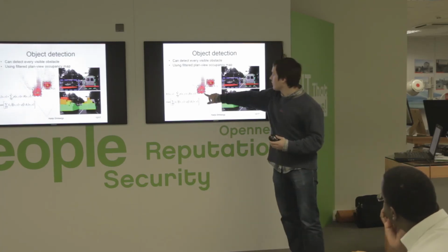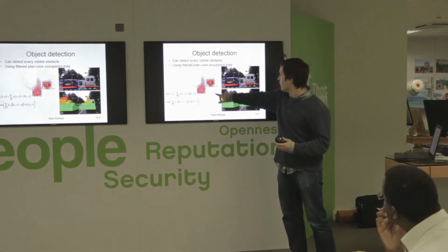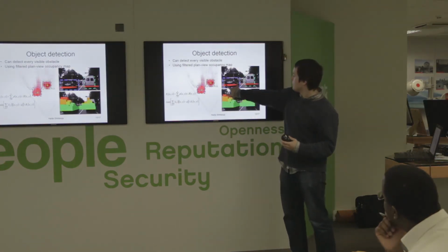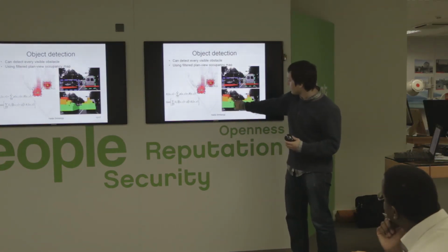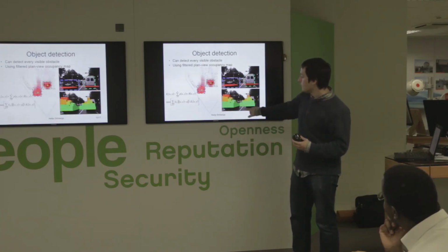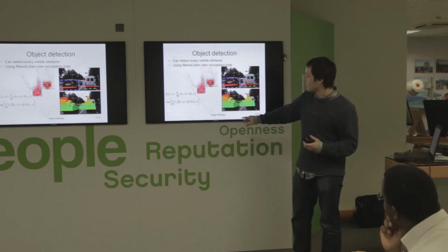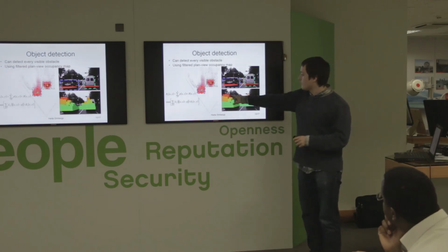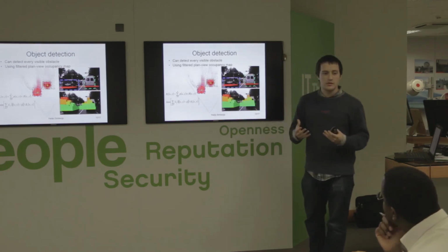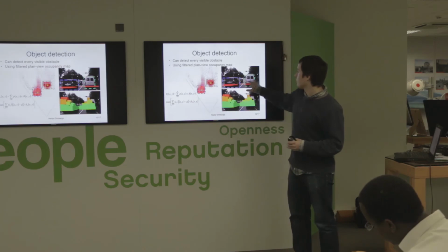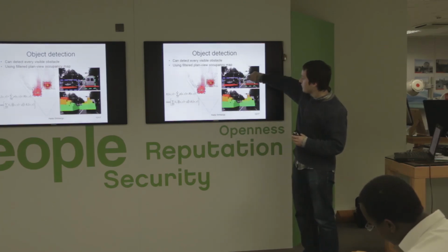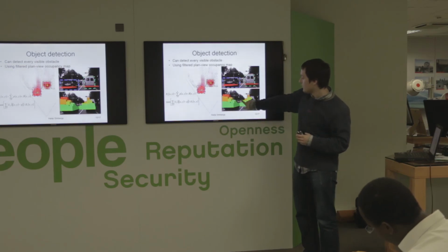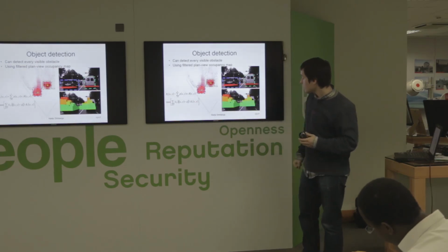For example, in this case there is the blue car here, the green car here, and here are the bins. You can see that there are a lot more points here and a lot more points here. The filtering is done by Gaussian filter, so you can actually see the Gaussian distribution. The maximums represent the objects. So I see, oh, there are two maximums and there are two cars. There's actually a third car in front, which is also detected, which is the yellow line underneath. You don't actually see any of it here.